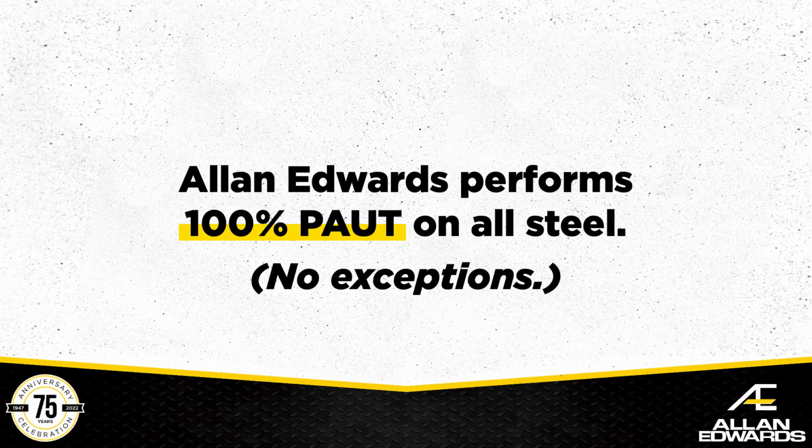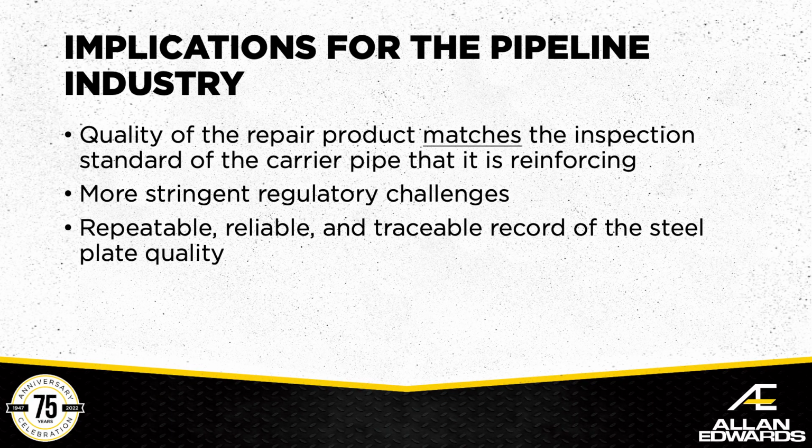So the main takeaway in all of this is that Allan Edwards performs 100% phased array UT on all of our steel. We do that as a standard, no exceptions. What are the implications for the pipeline industry? The quality of the repair product matches the inspection standard of the carrier pipe, as David's mentioned. There is no standard out there, so we've created our own standard. And our product, regardless of what the baseline inspection requirements are for the operator, across the board, it's 100% UT, no questions.